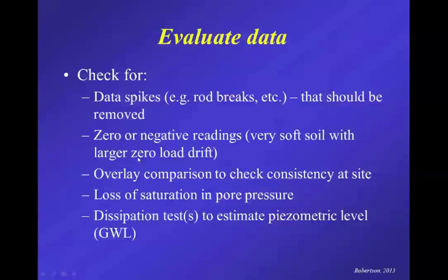And then sometimes if there has been a relatively large zero load drift because you're pushing in very soft soils, sometimes you get zero or negative readings on the tip or sleeve.